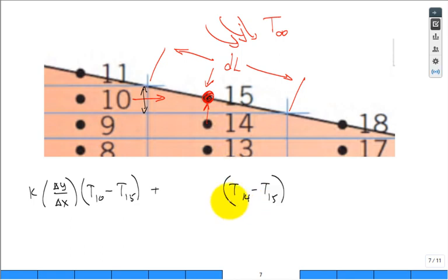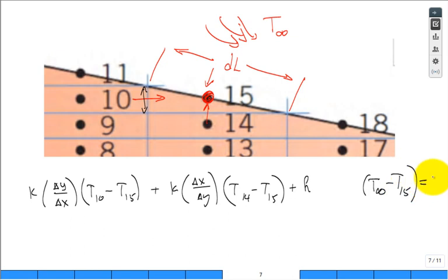That's the easy part. Put the K over here, slow down. What's my right area to length for conduction coming from the bottom? Delta x, distance, delta y. Then I put an h, then I'll put a T, what? T infinity minus T15. Everything's going in. Don't switch it. Don't now write T15 minus T infinity.